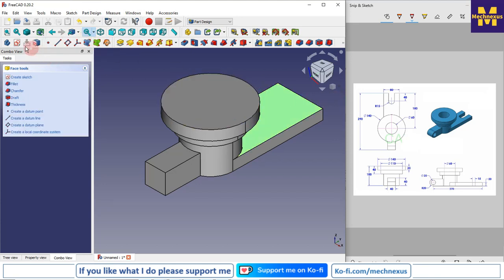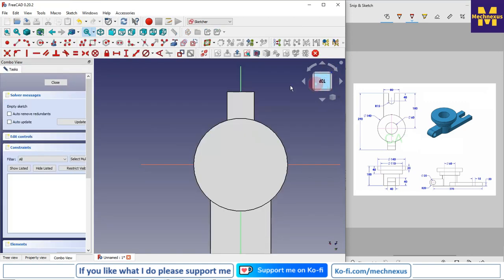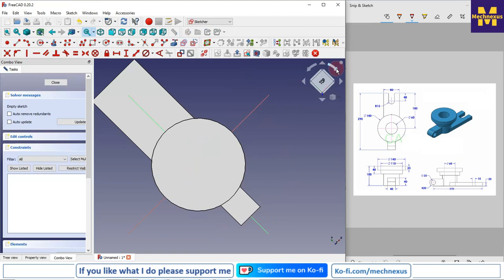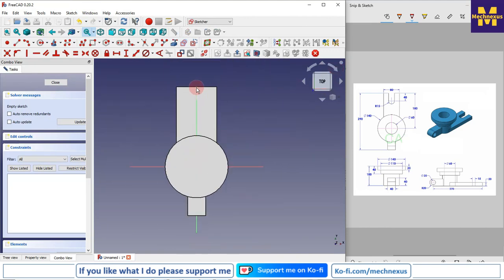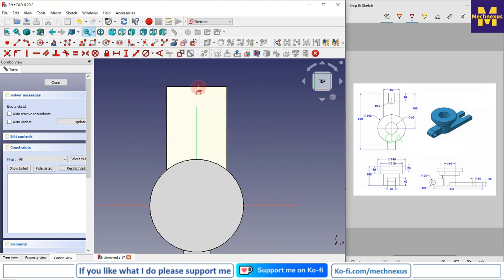I have selected the face and I will say sketch, and now I will project the outer edge, and draw the two lines like this, and I will make both vertical.